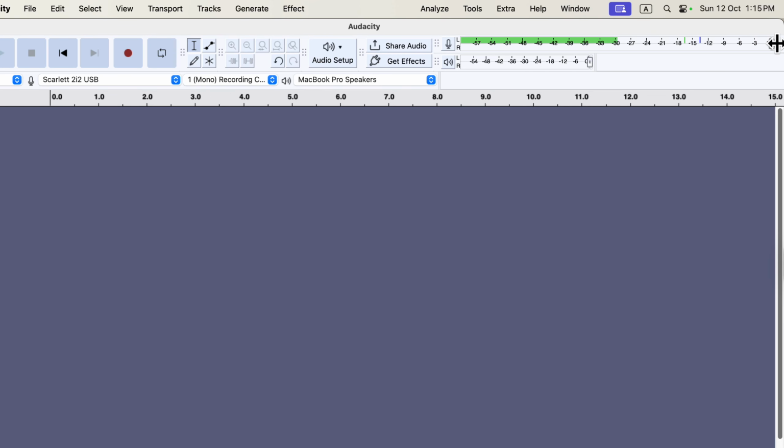While you are talking into the microphone, the levels should be between -18 dB and -6 dB. If your audio levels are in that range, that means you are getting good enough audio signals, and it is easy to process later. If your audio gets into the red region, there is a chance of distortion or clipping. Notice the maximum level on this meter is 0. If your level is more than 0 dB, you cannot see it, but your audio will be clipped or distorted.